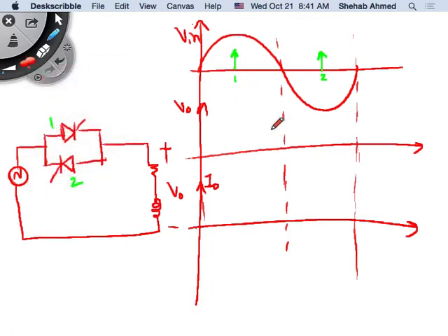Always think of the process, right? For the resistive load, what did the output voltage look like? It looked like 0 initially. And then when I provide the thyristor signal for thyristor 1, it looks like a diode now. If it's behaving like a diode, what will it do? It will conduct, right? It has a load here, there's a source here with a positive voltage, so it will conduct current. So thyristor 1 will conduct, meaning the input voltage and the output voltage will look the same, right?